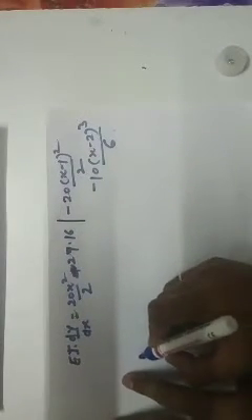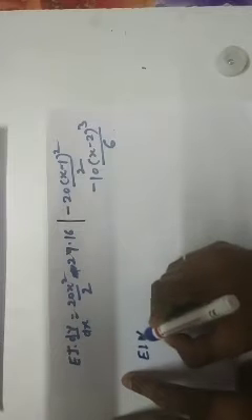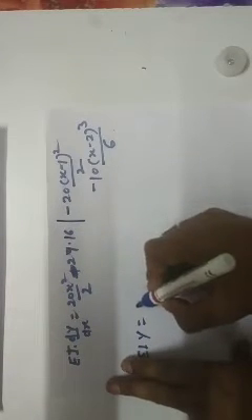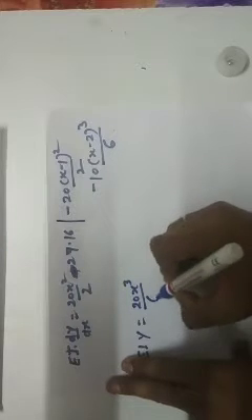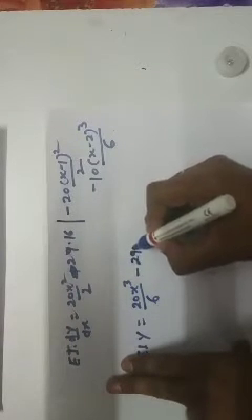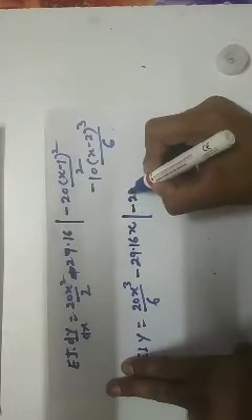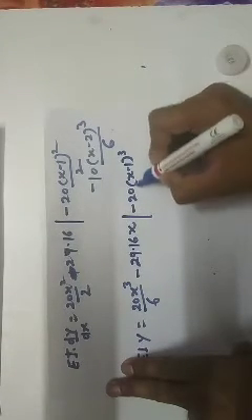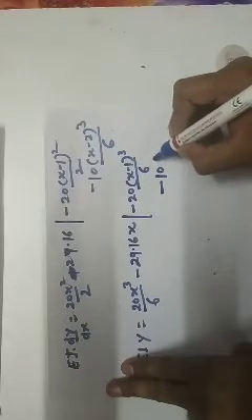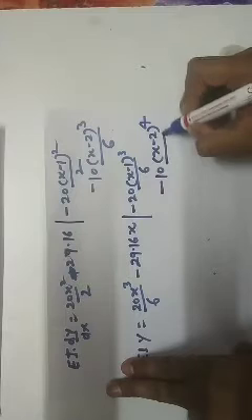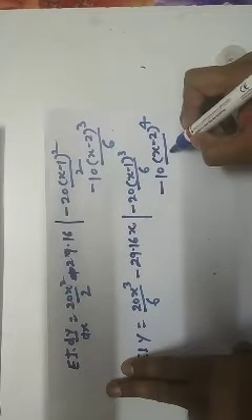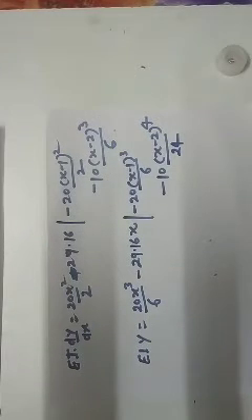Now what will be the deflection equation? The deflection equation will be EI y equal to 20 x cube upon 6 minus 29.16 x, C2 is 0, and here in the bracket minus 20 x minus 1 cube upon 6 and minus 10 x minus 2 to the power 4 upon 24, right? These are the two governing equations, and with the help of these two equations we will calculate the deflection at C.